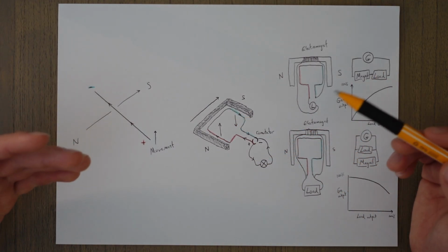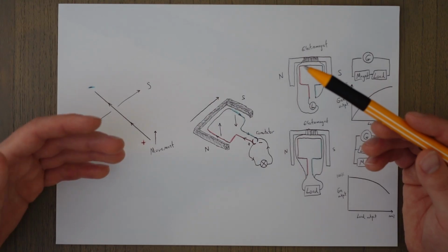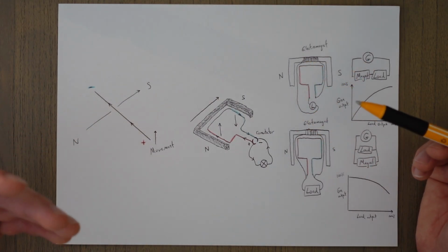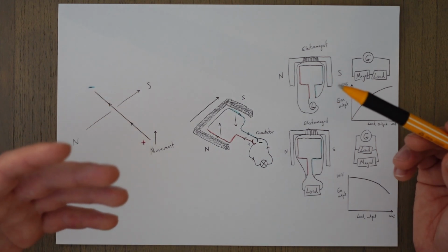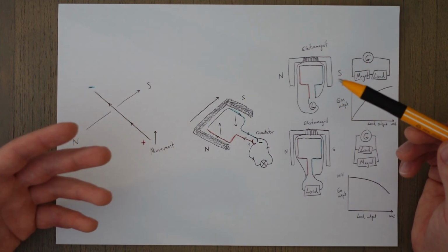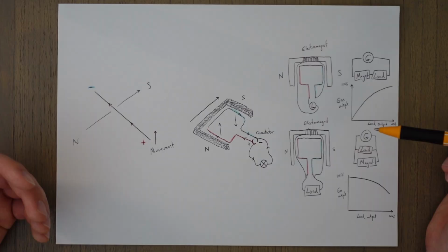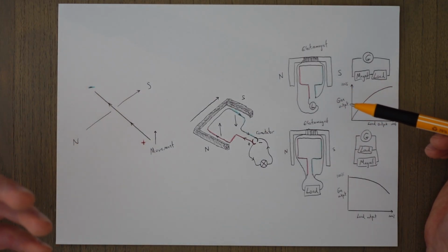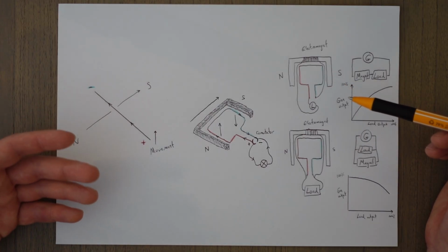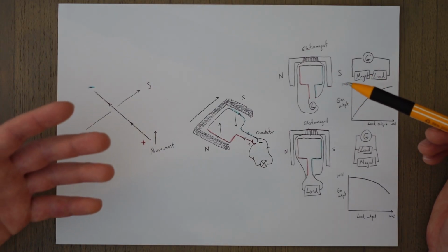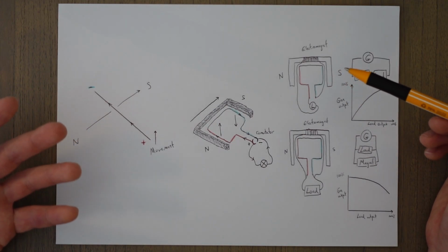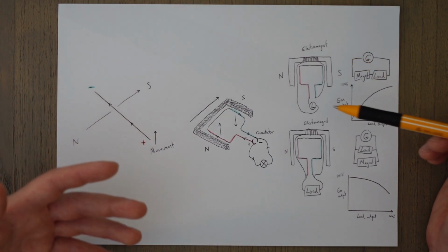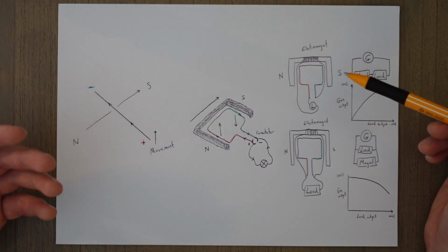Because using permanent magnets means a weak magnetic field and probably a low output current and voltage, we generally want to use and do use electromagnets for the stator in a generator. This way we can increase the output voltage because we can make the magnetic field stronger, and we can also switch these off whilst they're not in use and do not cause disturbances to other systems on the aircraft.